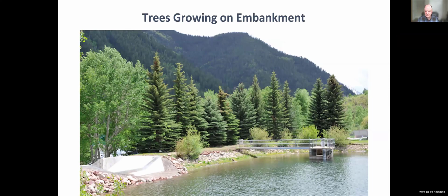And so here's a photograph of a dam, and you know, maybe you're not so concerned about this shrub here, but it's probably getting too big. Of course, all the ones in the background are on the downstream face of your dam. They're all too big. They shouldn't be there. So, you know, way too big. So this thing here has not been properly maintained. There's a spillway for this whole structure and a low-level outlet. You don't want them to get this big.